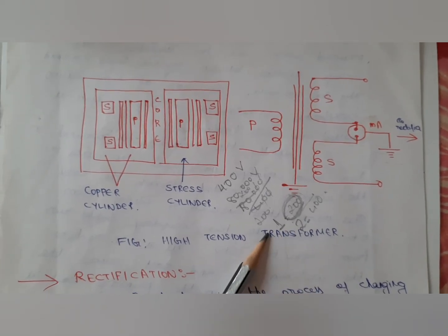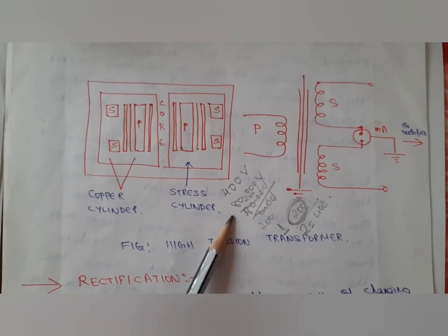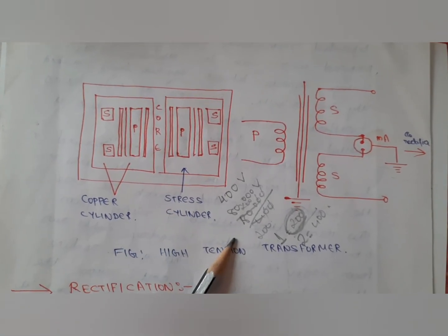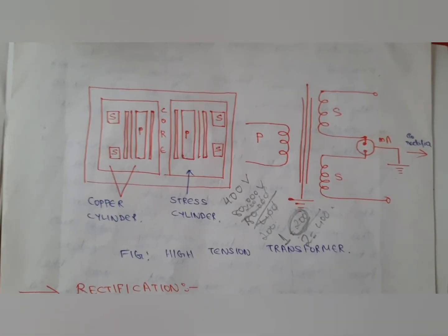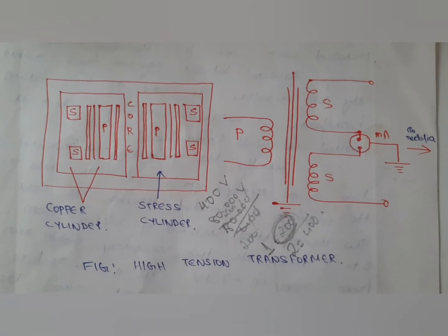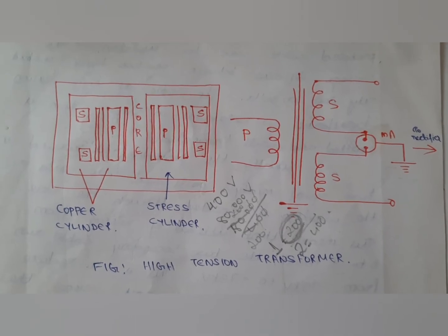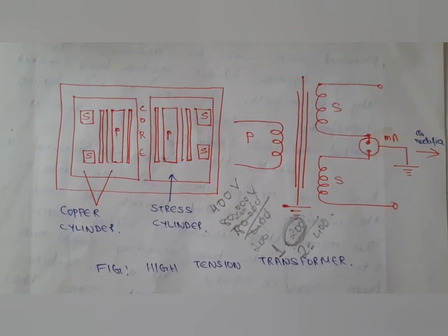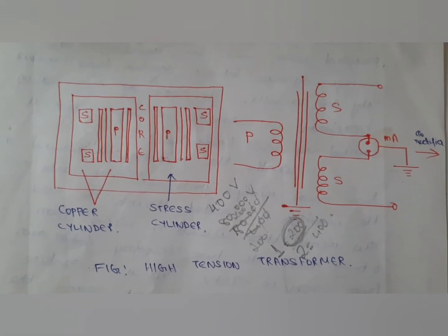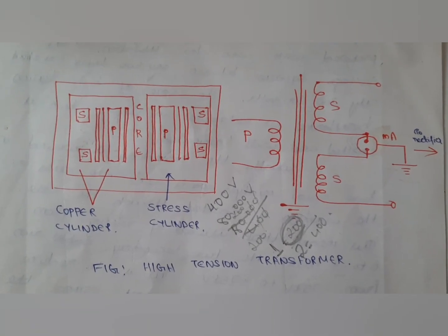Now in the high tension transformer that is used for portable X-ray and for dental X-ray equipment, insulating oils are not used because the heat generation in these equipments is comparatively less. That is why we do not use insulating oil in the case of dental X-ray equipment and portable X-ray equipment. So that was all about the high tension transformer.